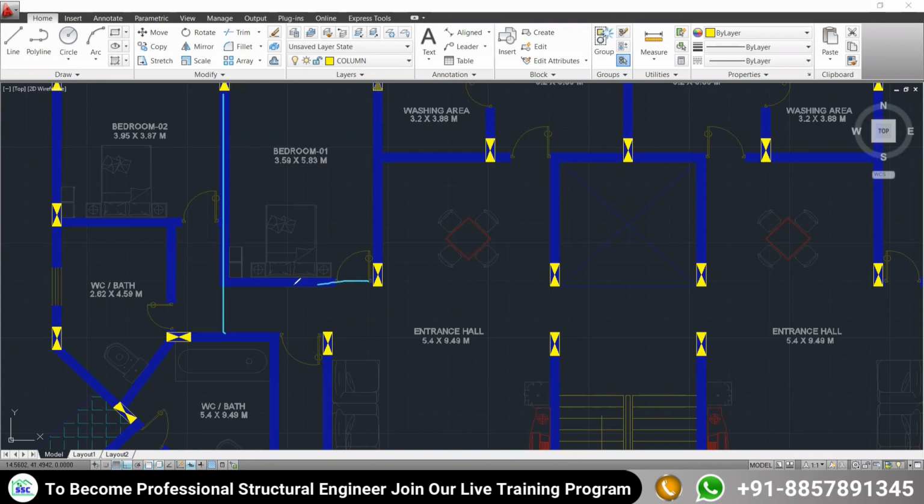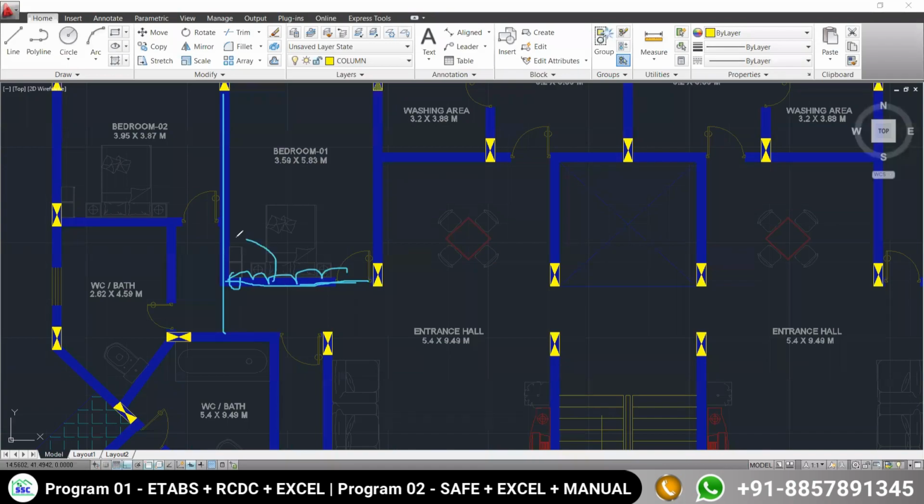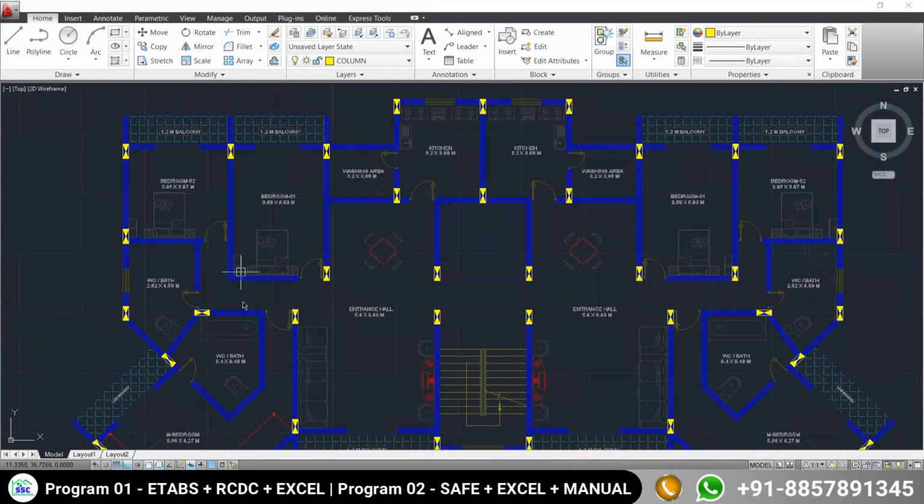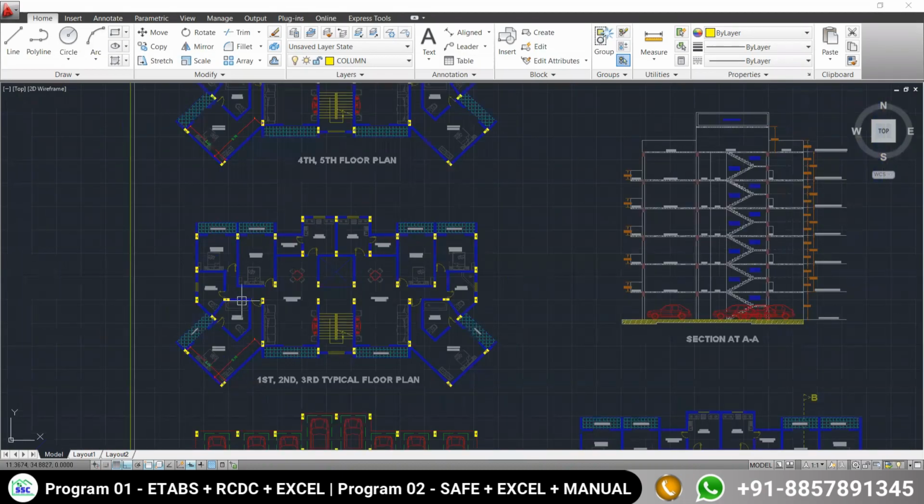Plus you are going to put additional beam load over this, because it is secondary. The load that comes over the secondary beam will ultimately transfer to this primary beam. So it is going to be a very heavily loaded beam. You can't continue here; you can't avoid this point.